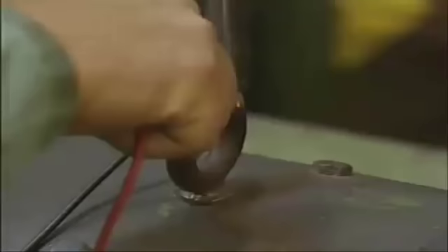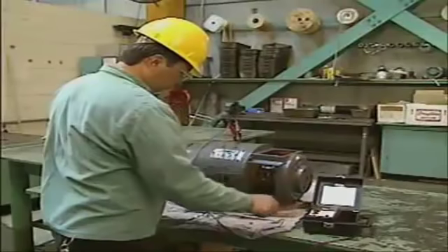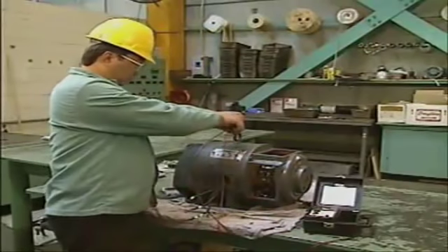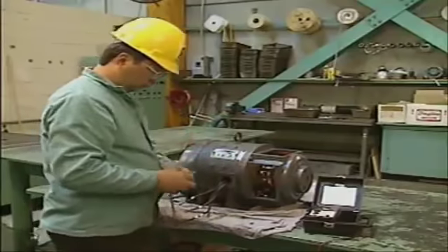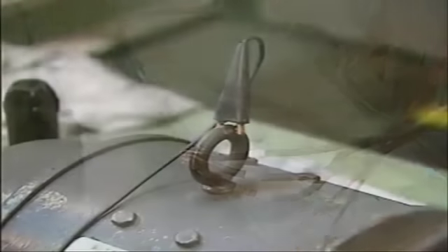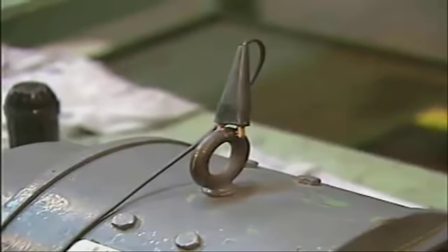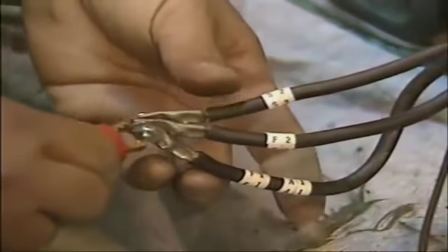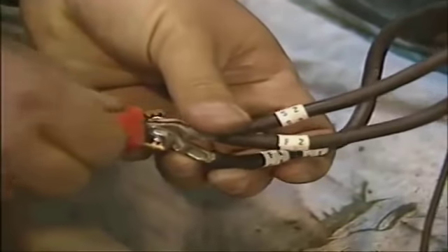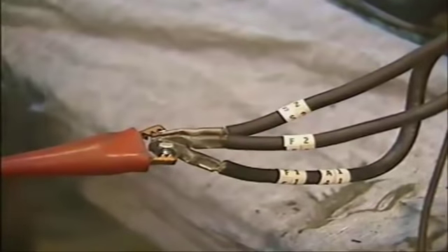Finally, connect both probes to ground and operate the meter. This time, the meter should indicate 0 resistance. If the meg-ohm meter is operating properly, it can be used to test the de-energized motor. First, the motor's 3 leads are connected together. Then the meg-ohm meter's ground lead is attached to a metal section of the motor, and the meter's line lead is connected to the motor leads. This arrangement provides a current path to ground if the motor is grounded.